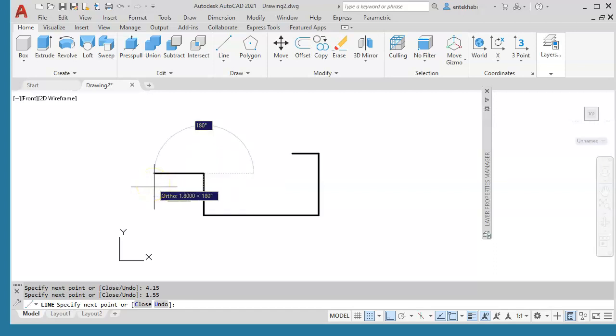And then you're going to go to the left furthermore. Your calculation is based on the center of the arc. You don't need to go the entire height. So your overall width in this case would be 5.75 from the right side to the center of the hole, which totals 5.75. So based on that, this is the profile you're going to create.